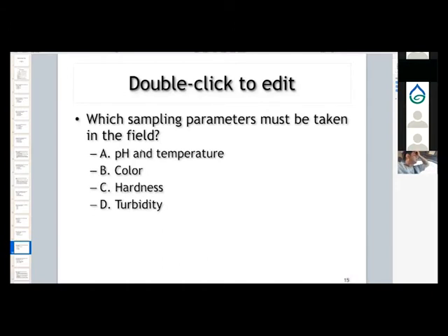So the coagulants adhere to the dirt. It combines, forms what we call floc, and in the sedimentation basin, through time and gravity, it sinks. And then the rest of the turbidity, which at that point is very small amounts, will be taken out through filtration.